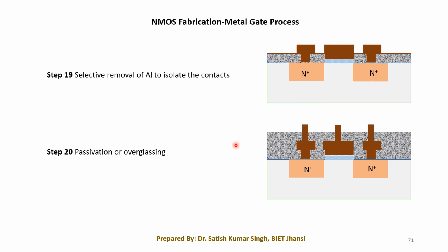There are certain processes like oxidation, doping, and patterning, in which we follow photolithography, where we place a positive photoresist, then use the photomask, and the photomask pattern is transferred to these devices. Then there is the deposition of different layers like metallic deposition or the SiO2 layer deposition. So many things are there.